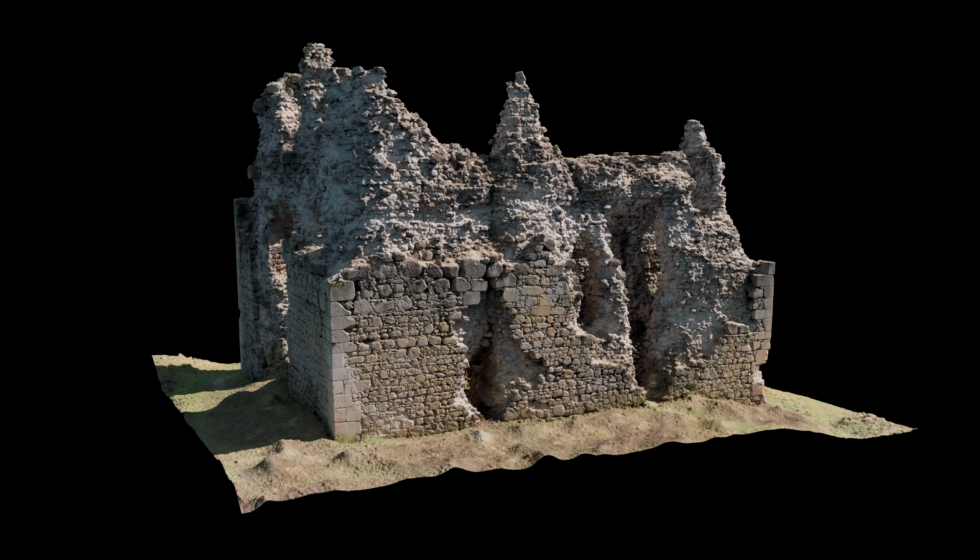Hello. Today I want to talk a bit about one of the new Houdini 19.5 SideFX Labs nodes called Spectral Feature Transfer. We'll go through a sort of prototype of how that node is built, and show you the basic idea of how to transfer certain frequency spectrums of detail from one area to another area, and how that's applied to clean up photogrammetry results.